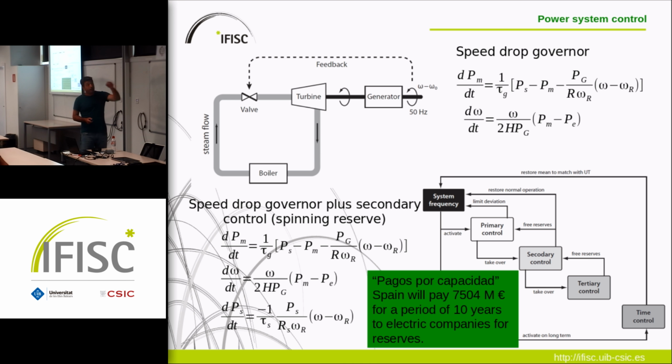Well, to have this control, actually, you need power plants which are not producing, which are idle. So you have to have some infrastructure just to compensate for the fluctuations of the frequency. Sometimes the demand increases, you bring those online, and you need that to compensate for that consumption.